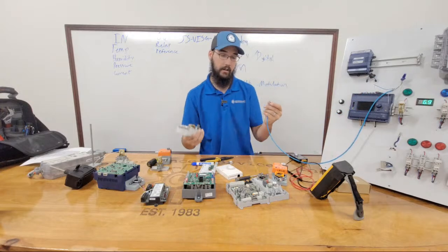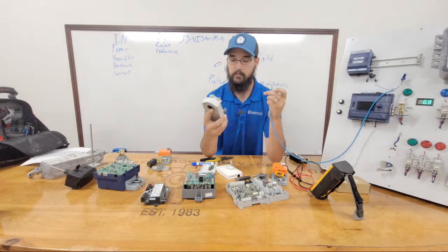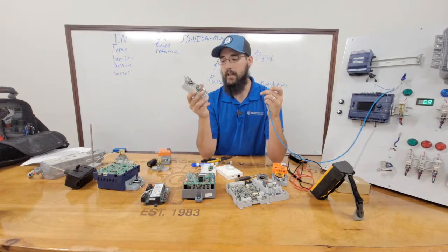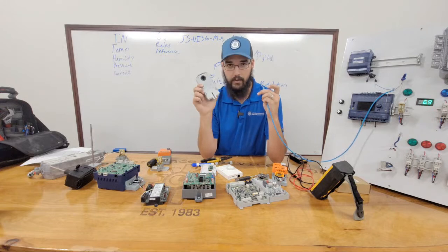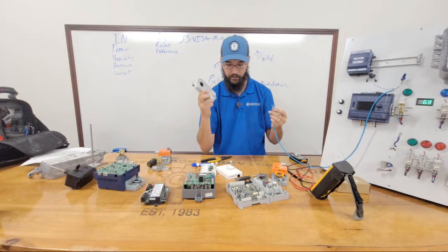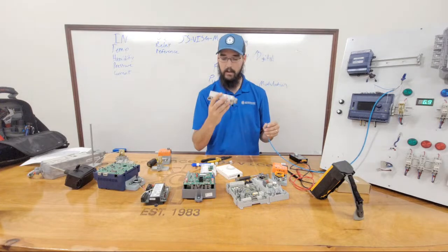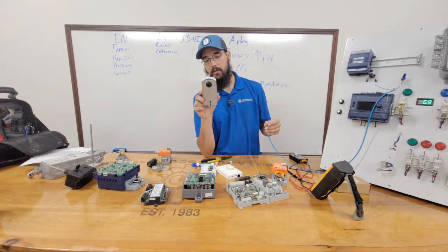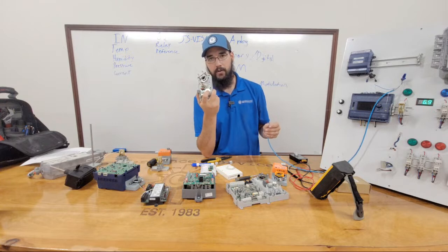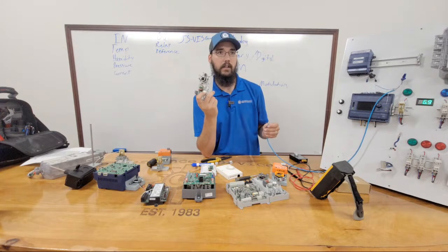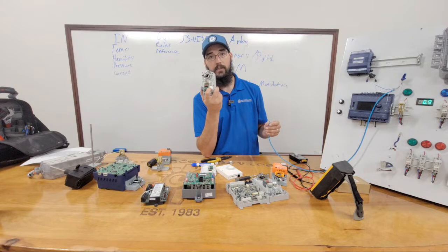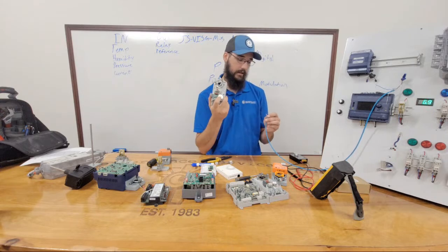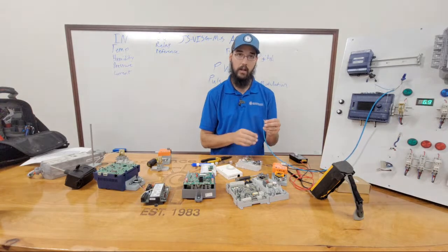Now I could do an entire class just on actuators alone. Ultimately, just kind of an interesting gee whiz with it. There's a whole gear assembly inside of this thing that makes it function and operate. This motor, when you hear it clicking or it comes to the stopping point, so when it torques out on a floating point, there is a clutch inside of here, and it's a magnetic clutch.